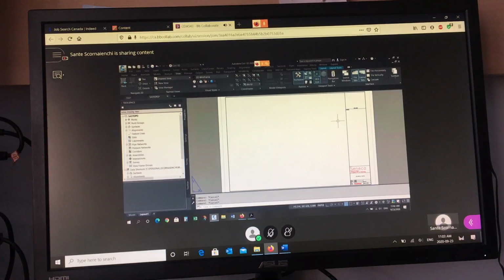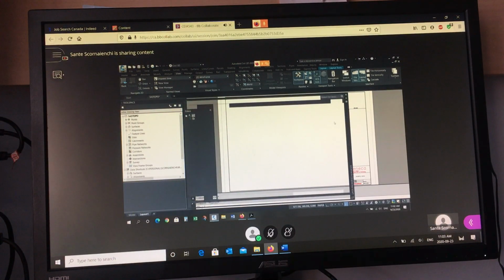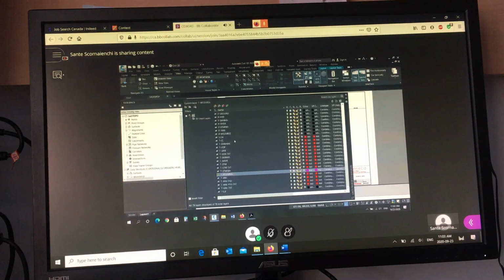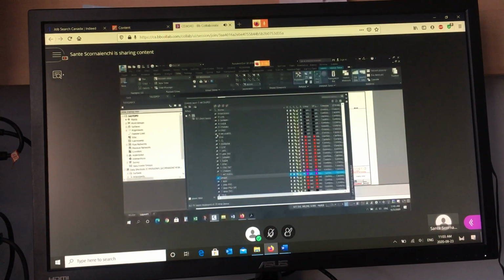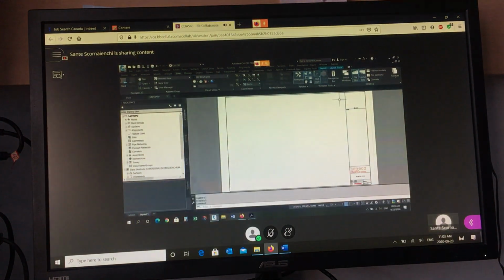So mview. To do this, I usually put it on a layer called viewport, and if it's not there, I would create it. And on that viewport layer, I don't want to see the frame, so I'm going to make it non-print. That's how you can see it in the drawing, but it won't show up on paper or a PDF, right? So when you print this layer, whatever's on it won't show. Okay, so I'm going to make it current, and it will not print. So now it should be current.